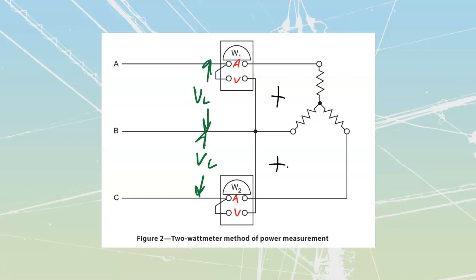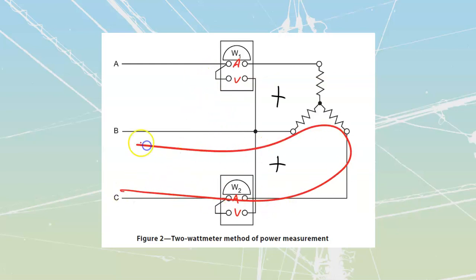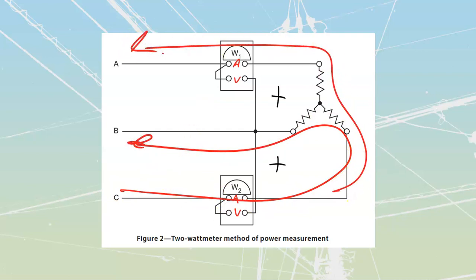And also, we're going to have surges. If you take a look at the way a 3-phase system itself operates, there are going to be times where all the power is being delivered along this line and it's coming back out on these 2 lines over here. So we're going to have a massive amount of power. We're going to have double the current coming through there for a split second. And then it's going to go from the C phase being like that to our A phase having both currents going through and splitting.